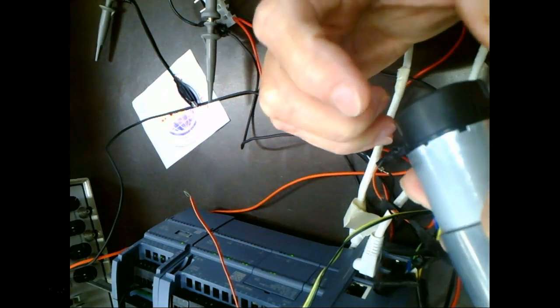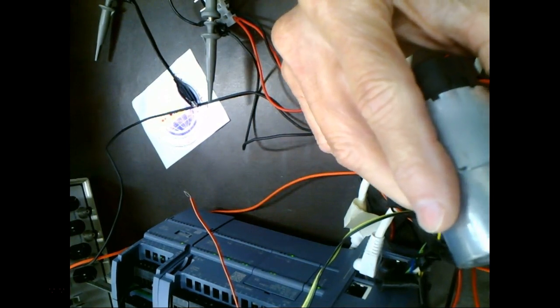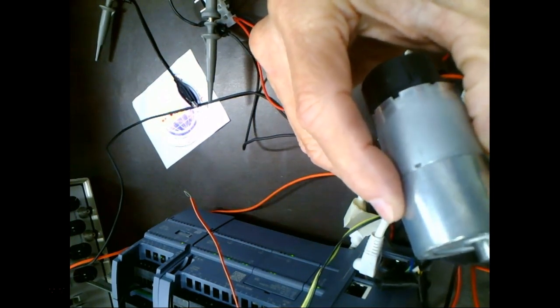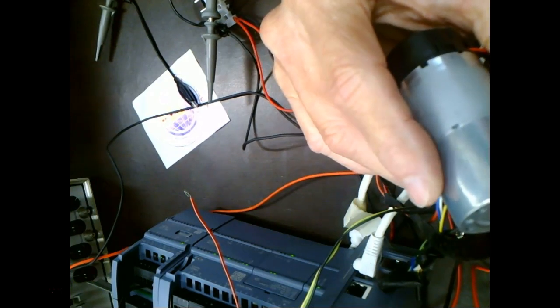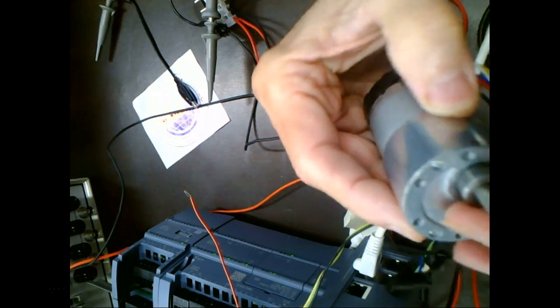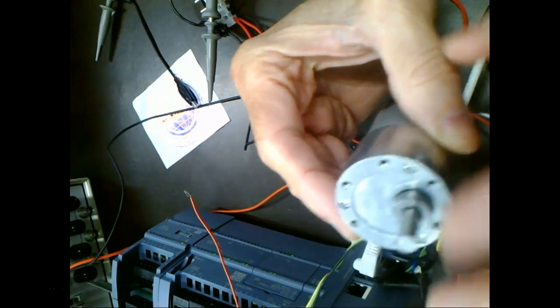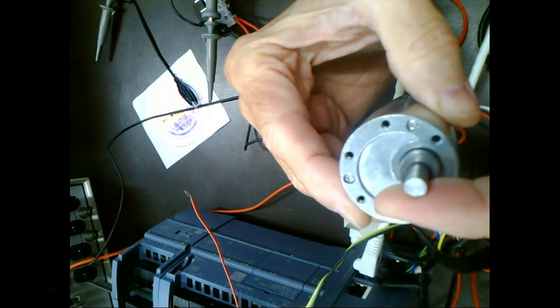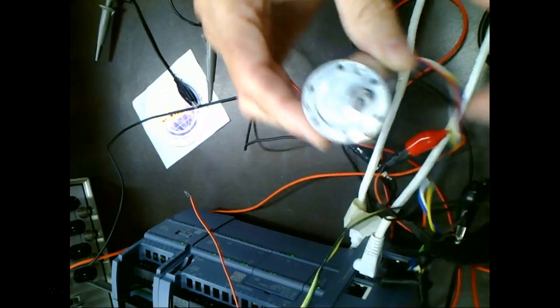So what we end up with is this encoder here, it's got 16 blades on it. But what we're doing is we're looking at the position out here. So we get 2,100 pulses for every one revolution out here. So that would be the resolution of our encoder. That makes sense? So if I know that, then I can figure out the position of the motor. Plus I can also figure out the speed of the motor, right? That makes sense.